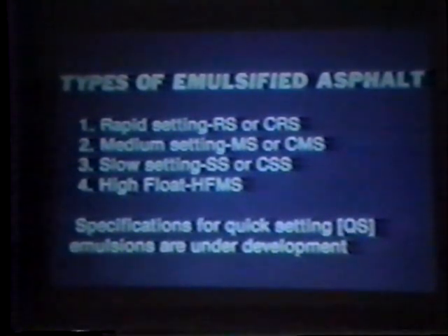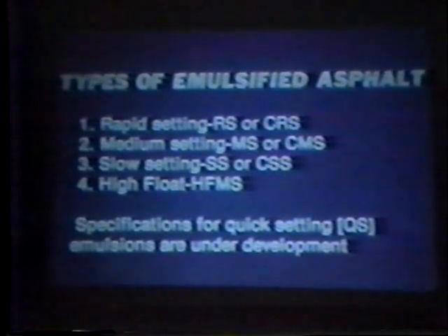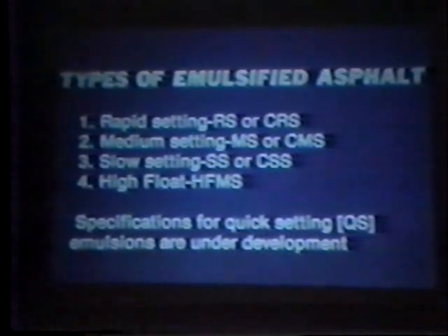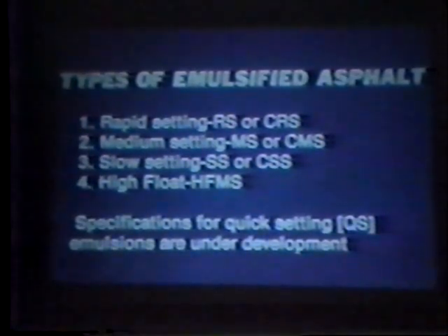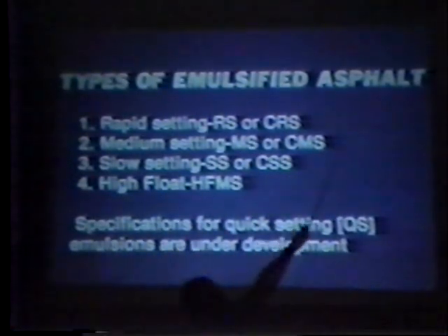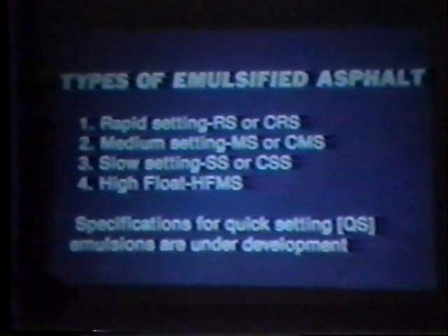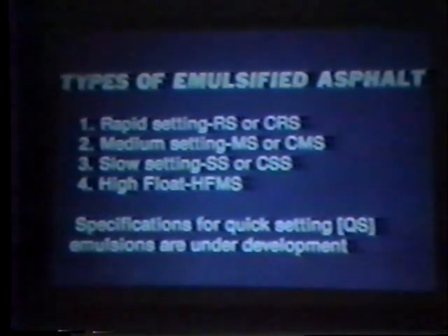And there is one more fluke, as I say here, because of the proprietary activity in emulsions. This has been identified recently by AASHTO and others, and we have to acknowledge it too. But it's really nothing more, and I kind of wish they had put it up here in parenthesis next to a medium set. It's a product called high float medium set emulsions. And the only difference is that when they run a test on the asphalt cement that's used, there are different properties that are measured. The proponents of the product claim different kinds of virtues of performance with it, and we always have to defer those claims naturally to their own documentation. We don't have any to document one way or another.